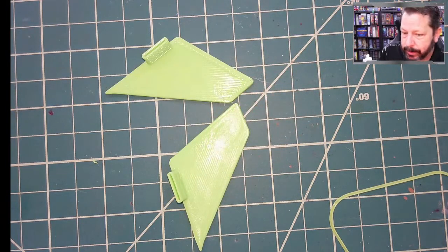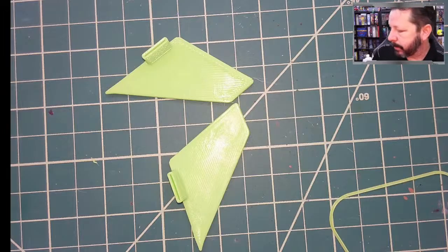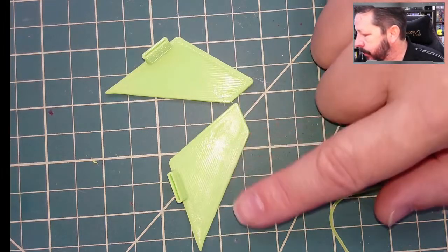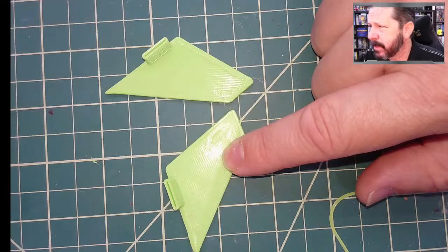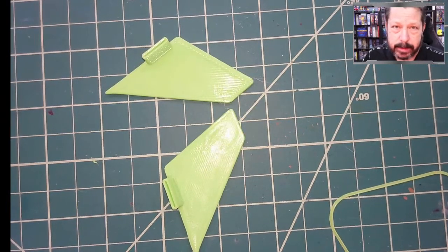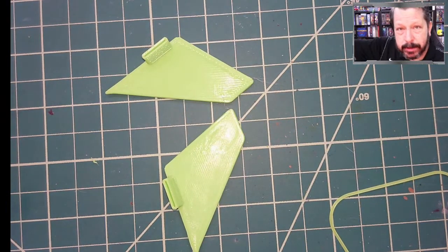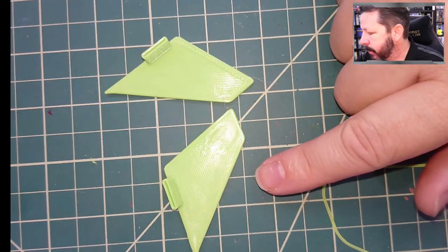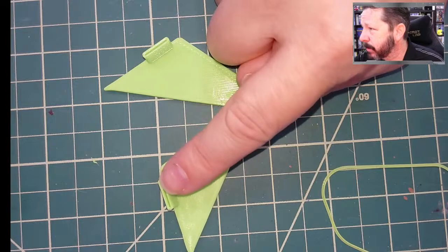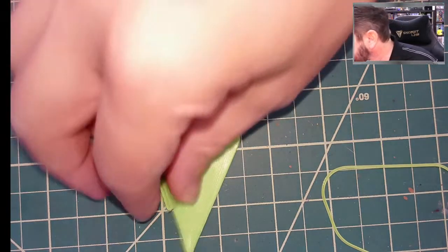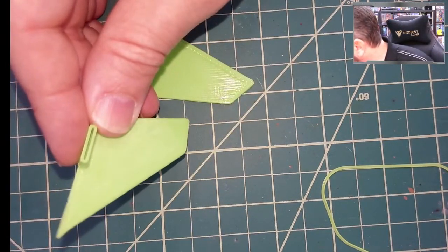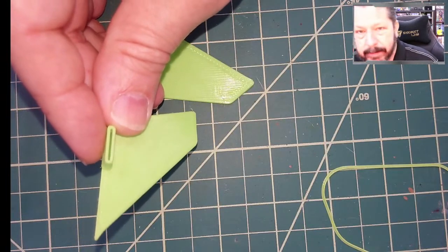There is a way to do that, but it's not in most slicers. So it does have to be a flat surface, which this is, and a top surface. And it can either be the topmost surface or any top surface that's flat. I think I did any top surface, otherwise it would just iron that little piece up there. So it does make a difference, and you can tune it to make an even better difference.